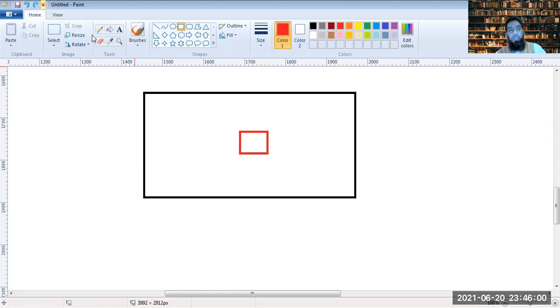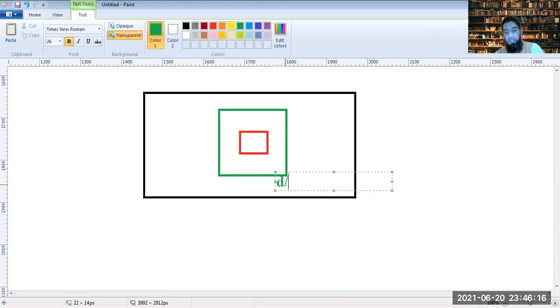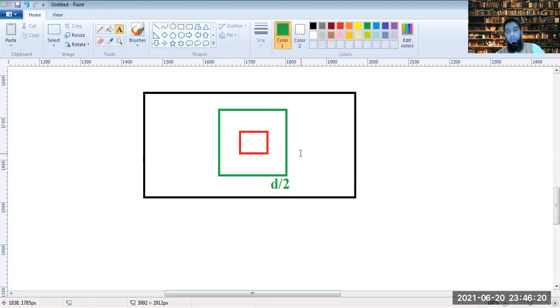Now a two-way shear usually occurs as a punching mechanism in this plane. Now this plane is at d by 2 on all directions.